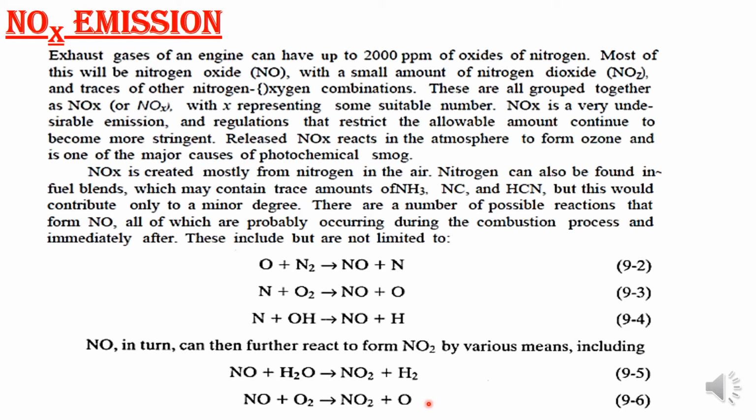The NOx concentration in the exhaust is affected by engine design and vehicle operation. Air fuel ratio and spark advance are the two important factors which significantly increase NOx emissions. The maximum NOx is formed at an air fuel ratio for an SI engine between 14:1 and 16:1, just near stoichiometric. At lean and rich air fuel mixtures, NOx concentration is very low. Also, increasing the ignition advance results in high peak combustion temperature and high exhaust temperature. This will result in high NOx concentration in the exhaust.